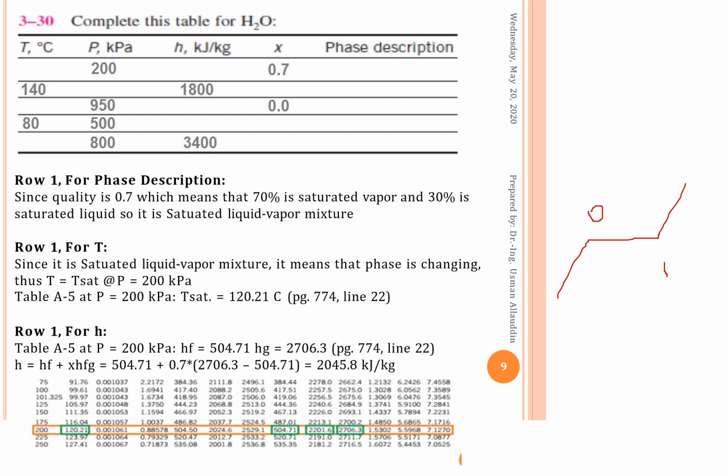So we know that our compressed region is here and the superheated region is here, and our values start from Vf, which is 0, and Vg, which is 1. At superheated, V does not have any value, and the same is the case for the compressed region. So on those blocks, for the compressed region we write nil, and for the superheated region we also write nil.